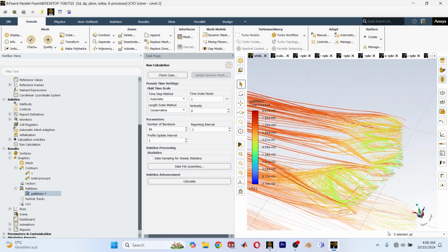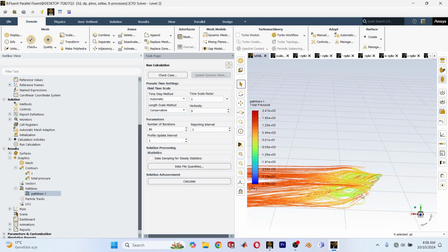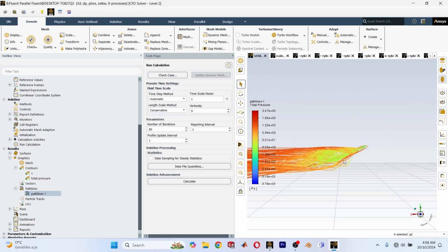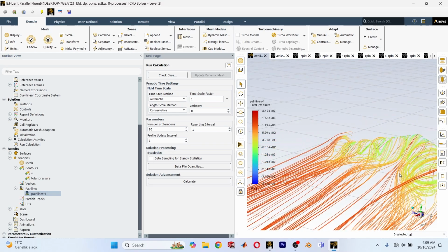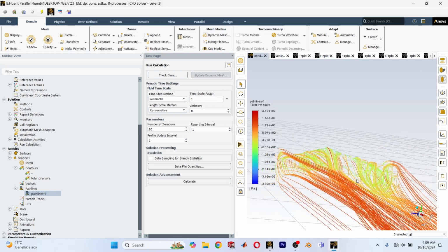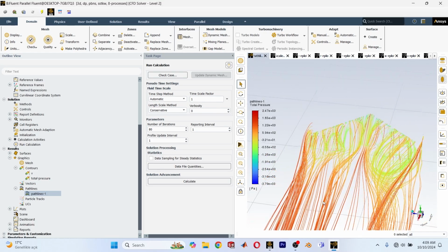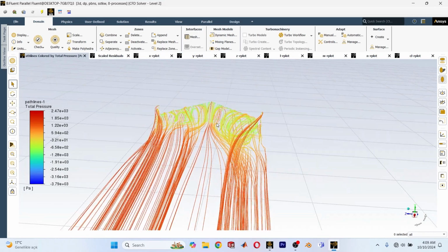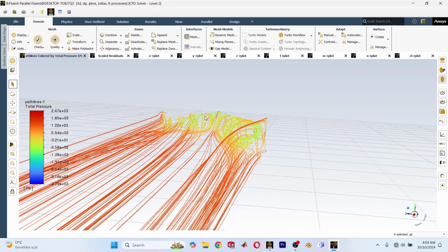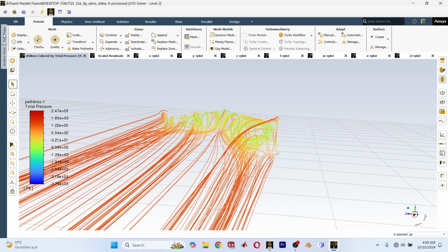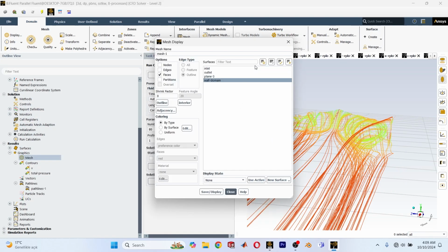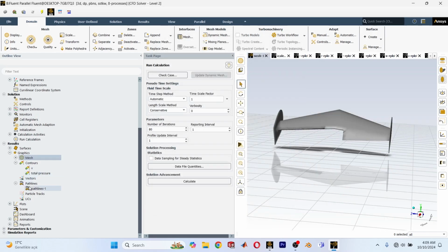You might say that there is something wrong, but maybe because of the stalling. Okay, this is a 24 degree angle of attack, so maybe the aircraft is going to stall. Do you see that? Maybe we can add the aircraft. Let's add a new mesh of the aircraft, save and display, and add this to the active window.